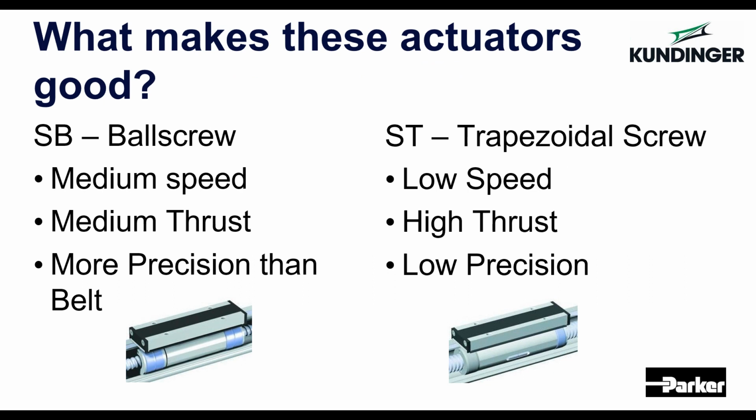Now, there are trade-offs in this case. You do give up precision and speed and duty cycle, but if you're in an application where you're trying to keep it low cost and don't have the ability to add any kind of a servo or a fail-safe holding brake, typically you're not really going to care too much about your precision.